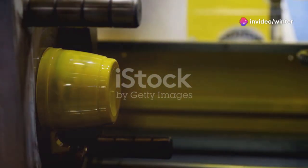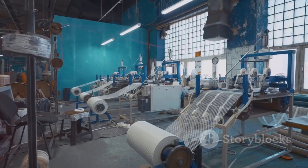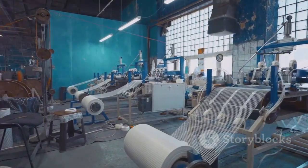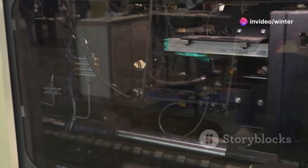Now let's talk about runners, the channels that deliver molten plastic to your part. Cold runners are simple and cheap, but they create waste with every shot. Great for low volume runs, but material waste adds up fast in high volume production.